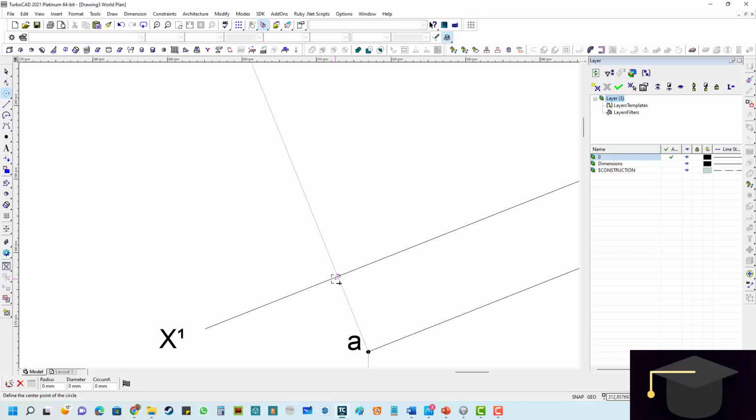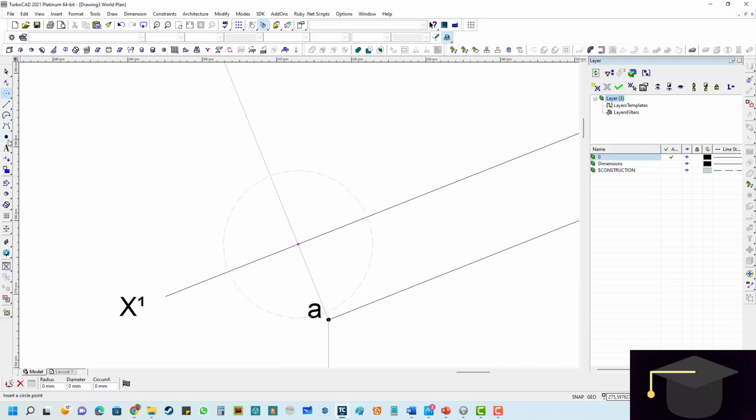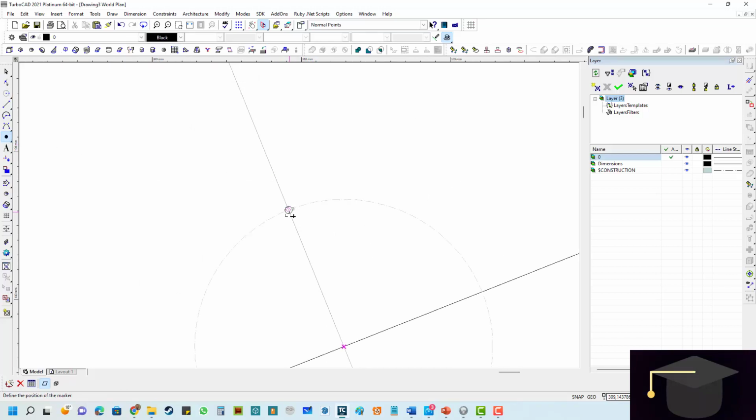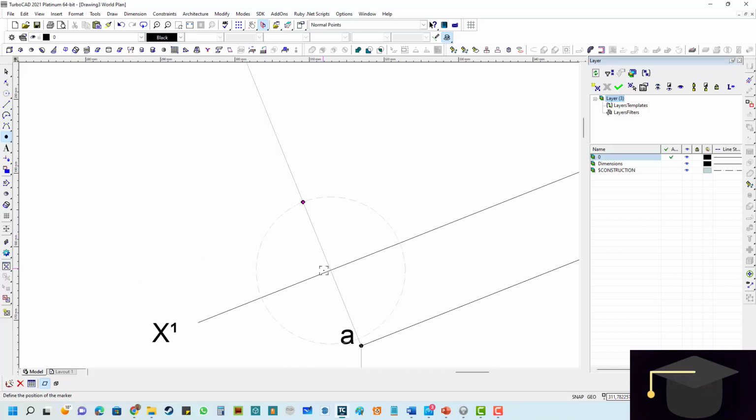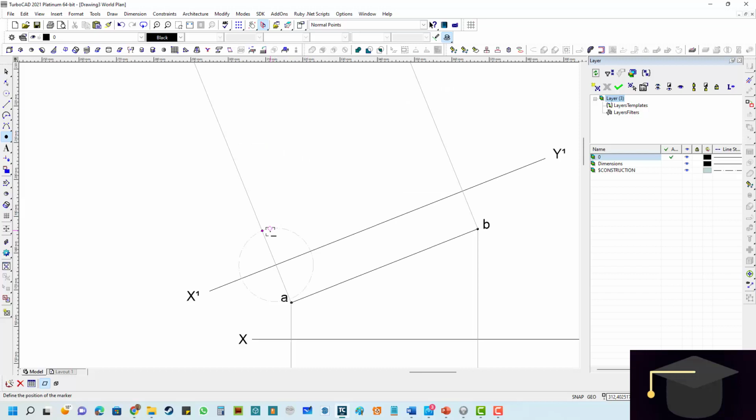Then at the X1, Y1, we place our divider and carry over that 10 millimeters to that projection. Now we know that reference point A2 will be over there, because that's the next value. We've already used A in the front view, A1 in the top view, and now in our projection we will use A2.